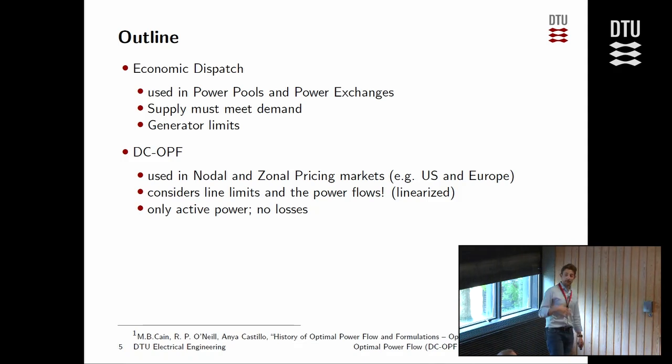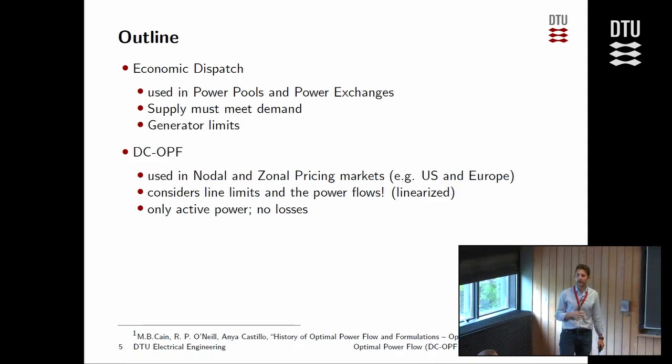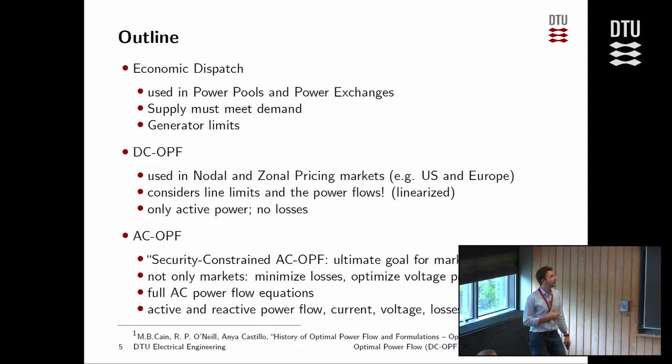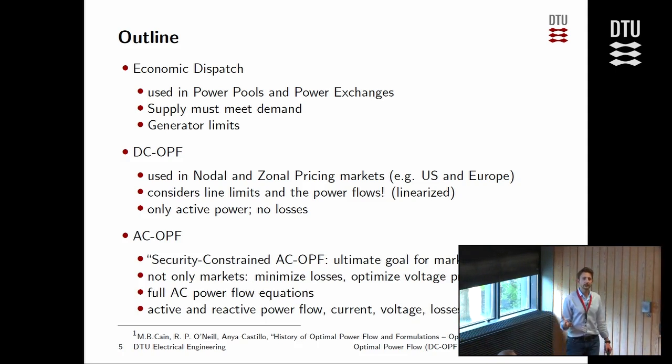It considers the power flows and the line limits. However, we have only the active power. We don't take into account losses or reactive power. And the AC-OPF is, let's say, the full-blown problem. We have the exact equations there.